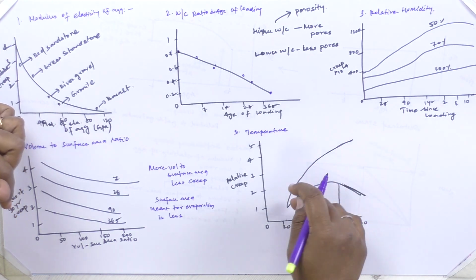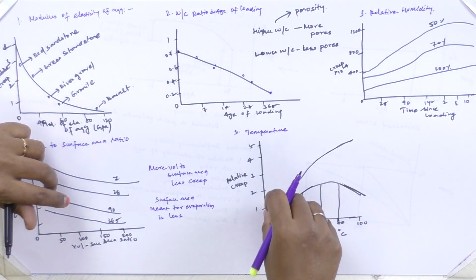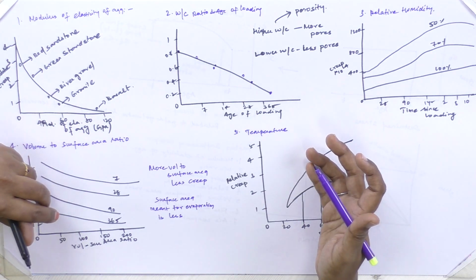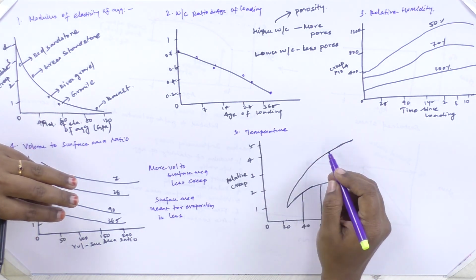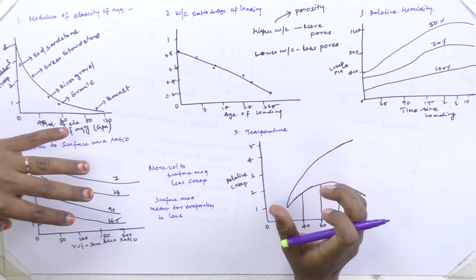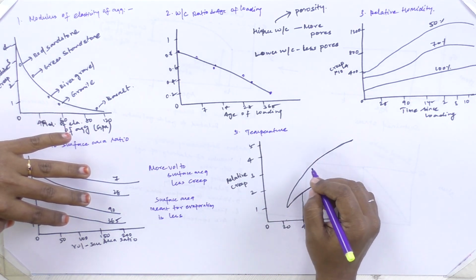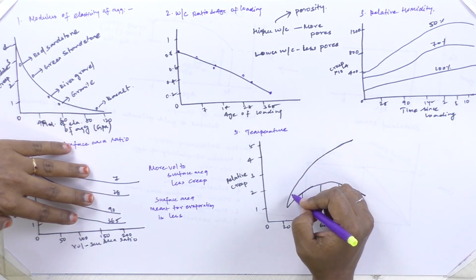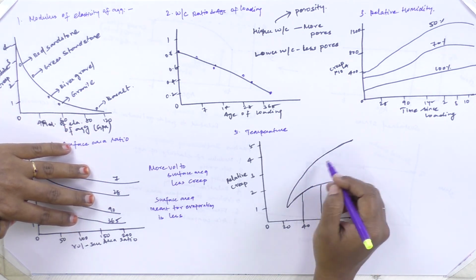Whereas here I am curing at one temperature, and before applying load I am heating it to the test temperature, and because of that variation I will be having movement in the gel water system, and so I am exhibiting a higher creep.